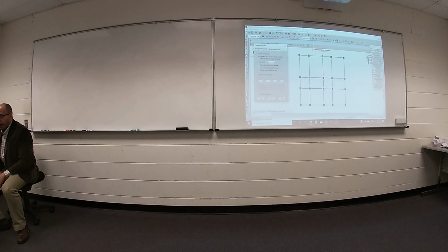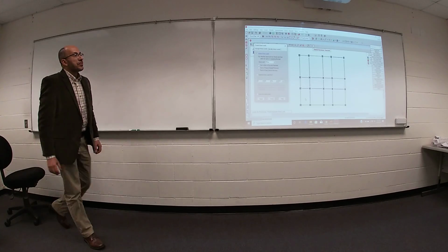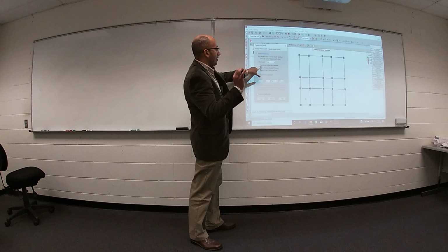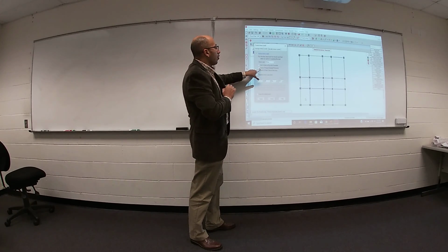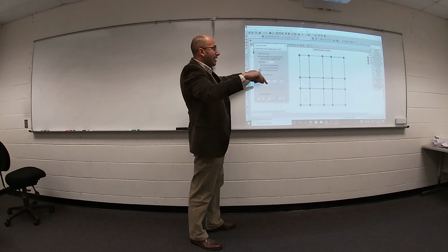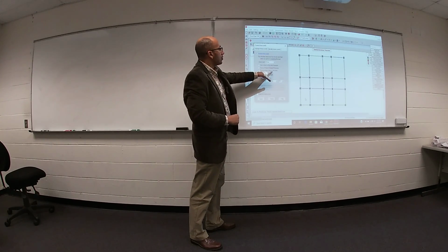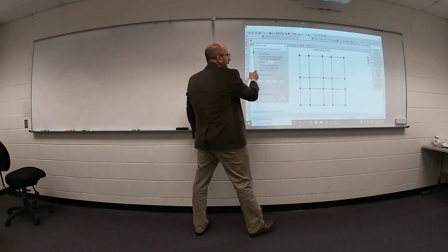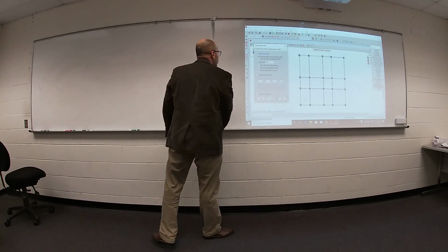Office, apply. I tried it but it doesn't work. Why? Because I have three options. You can define your load by just clicking within the perimeter of your area, or draw a polygon area around the perimeter of your slab, or point to point draw of area. I need to click here, click, click, click. So you have three options to define where is your load.